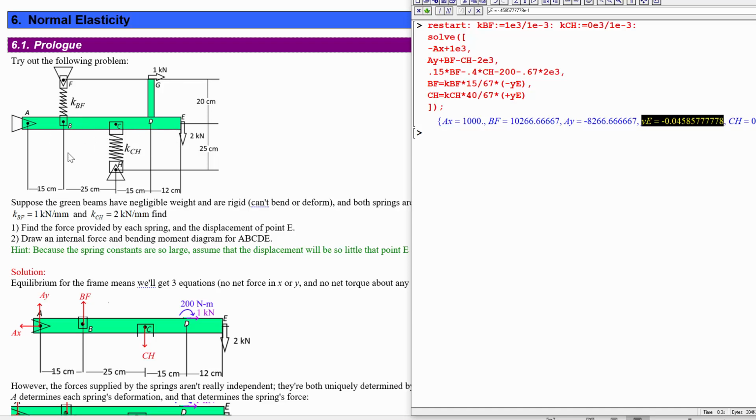So let's see why this works. We've got it at half the distance, which means it's going to produce half the torque. And then it has half the spring constant, which is another factor of 2. And then there's half as many springs helping out. So it needs to do a lot more work. So those 3 factors of 2 give us like an 8.